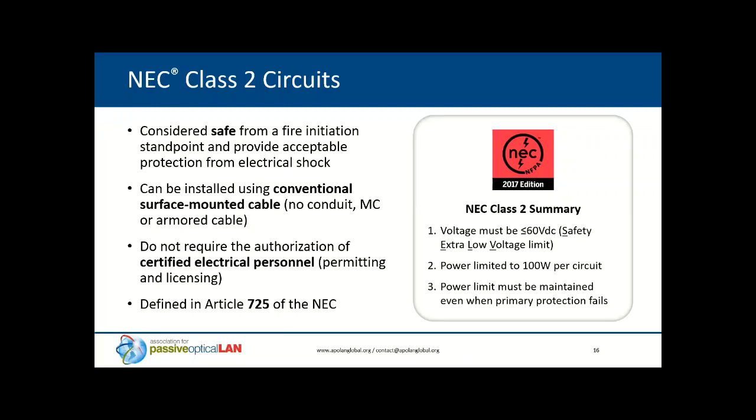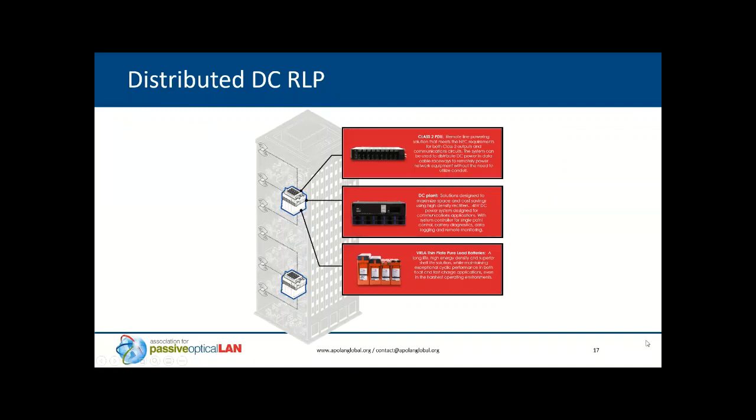So essentially what that means is that you can have an isolated circuit or another form of secondary protection, and this will really eliminate the use of fuse panels or a breaker panel in this application, steering you down the path of using a true Class 2 approved and certified PDU or DC to DC up converter, if you will. Now we'll go into 2 examples of really how the architecture is laid out throughout a building.